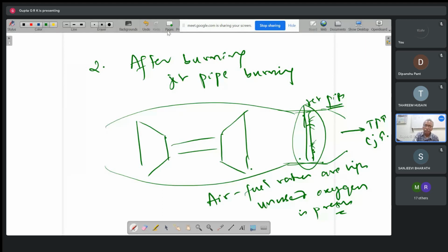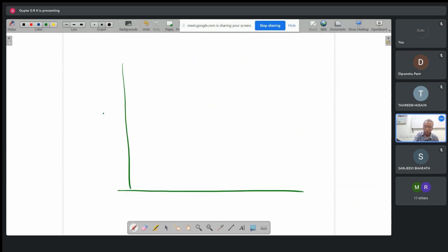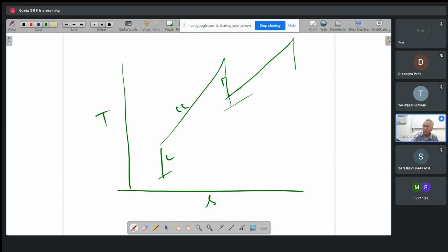The advantage is, so after this is turbine, compressor, combustion chamber. And here, after the turbine, instead of expanding here to the nozzle, the temperature is increased like this. So this will be the thrust. This is the nozzle power I will get. So the advantage, suppose this is 1200 Kelvin because of metallurgical limit.